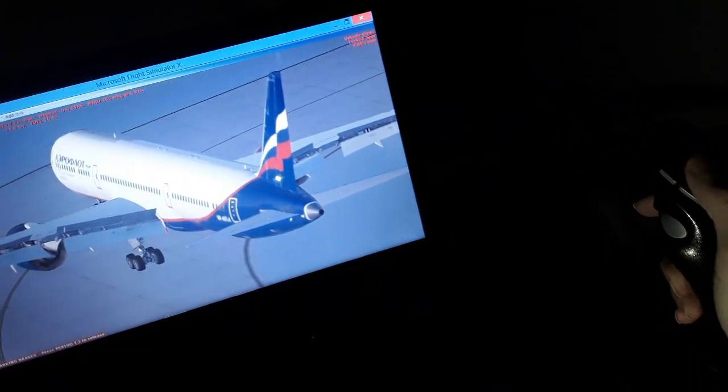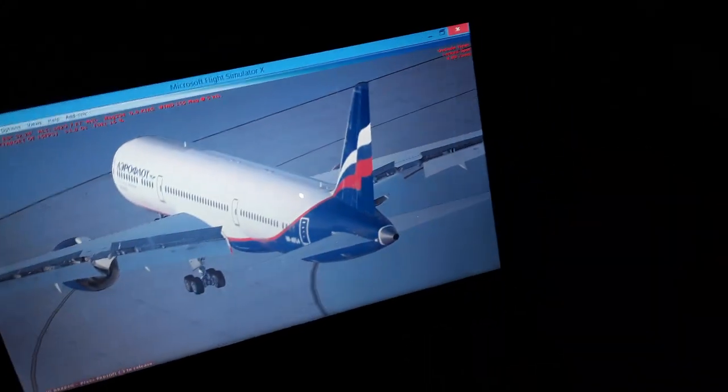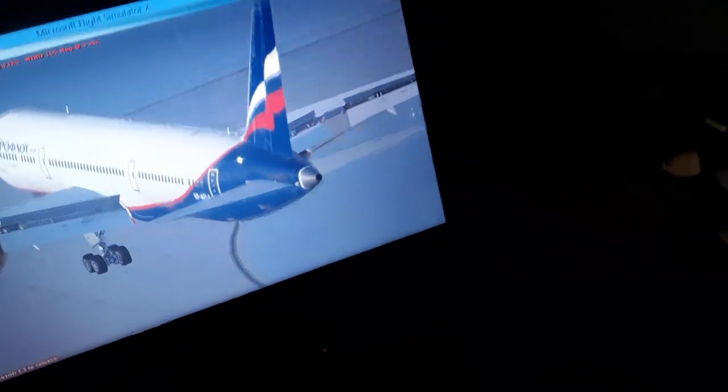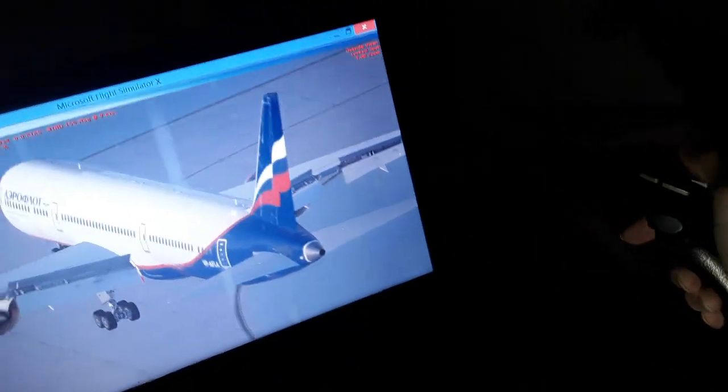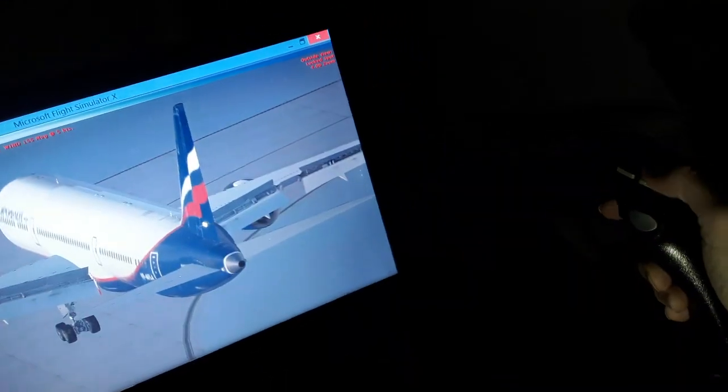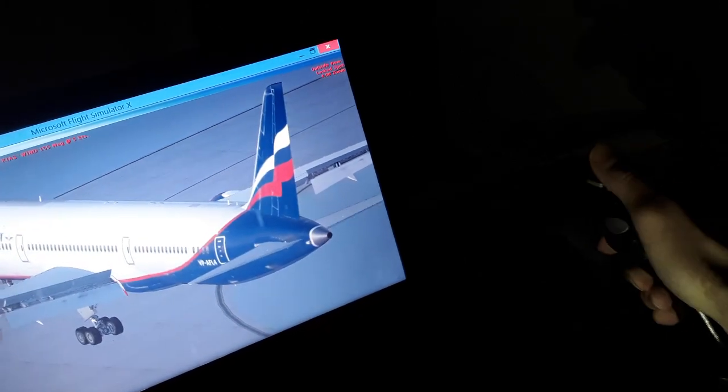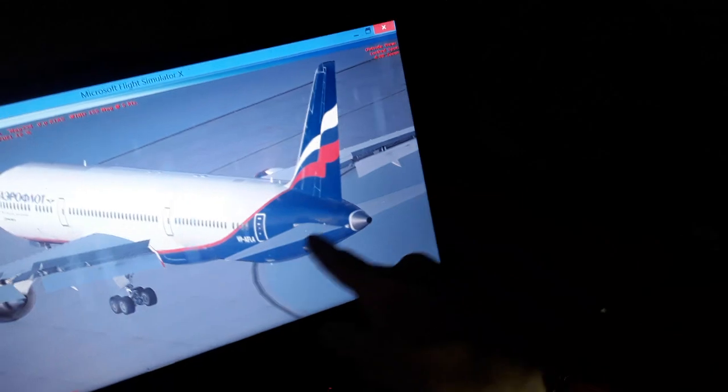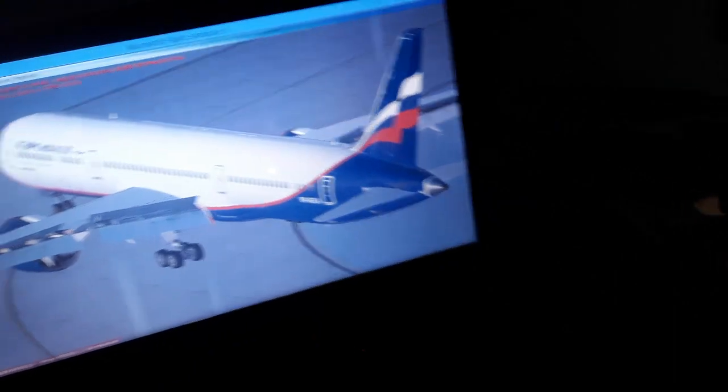We can pitch the aircraft up and down for climb descent like this using the wingtip. The pitch axis over here from wingtip to wingtip transverses the other axis, so we climb and descend using the side stick in the Airbus or the yoke in the Boeing like this. So you descend and you climb. So you have also the horizontal elevator trim, or some aircraft have this one has the elevator trim, others have the horizontal stabilizer trim. The stabilizer trim is trimmable.